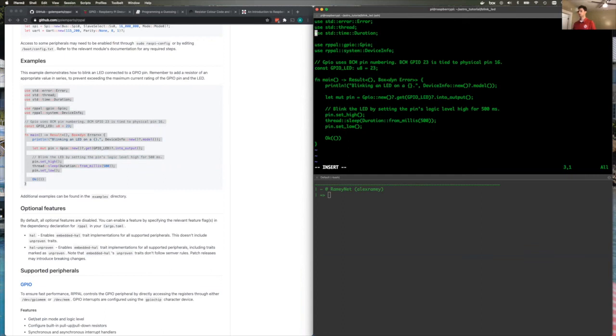It's got, including some of the standard library stuff. This is using the actual packages that we just downloaded, the GPIO package. This GPIO LED for us, it's number 4. Yeah, it's number 4, and they're talking about the BCM pin numbering versus the physical pin numbering. But yeah, we use that pinout diagram to see that the GPIO pin we're plugged into is BCM number 4. So we set this to 4.